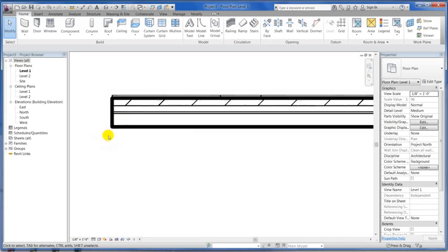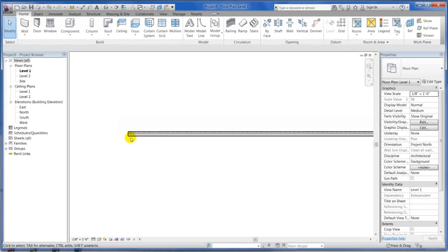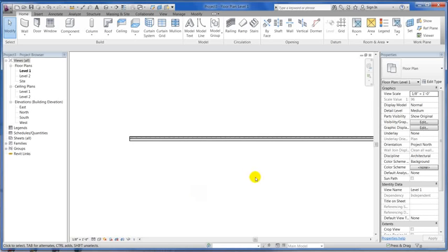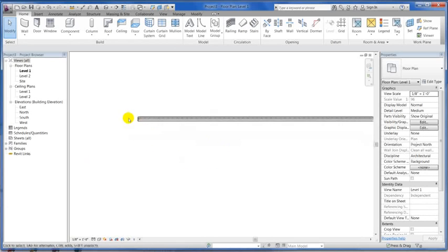And you'll see that some of the layers are darker, some of the line types are lighter. I don't have to worry about layers and colors and all that stuff that AutoCAD makes you worry about. It's in there, it's in the wall properties, and it can be modified. You can make it your own. But for right now, it's just easy out of the box stuff. Revit doesn't worry about that stuff. It looks like a very simple user interface, and it's done that way on purpose. You don't have a lot of options up front, but all these walls, doors, windows, families, they're all very smart, they're all parametric, and that's what makes Revit a great program.